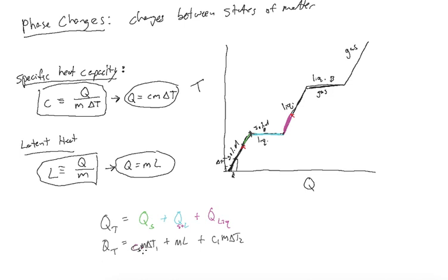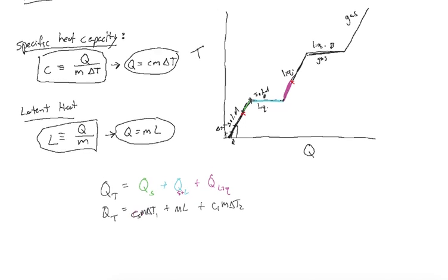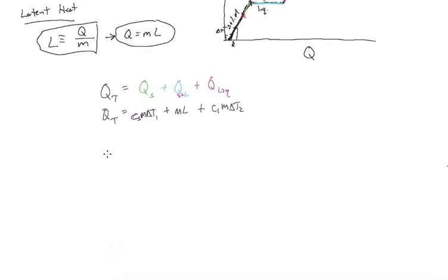I put this much energy in here. If it stays as a solid, then I'm done, I just calculate delta T. If there's so much heat that this amount here is fully covered, then you have to see, does it get me through the phase change? All right, this amount and this amount are totally covered. Then how much heat is left over? Then I apply that much heat to that and see how much the temperature change would be.